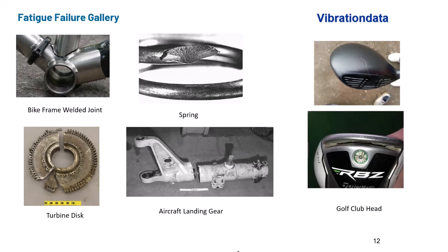The pilot has to do a slight pitch up or flare of the nose prior to landing so that the back wheels touch down first, and then the nose gear following that. All those factors will determine the G level. Now, the G level in landing is monitored on all these commercial flights that you've taken. If the G level is high enough, that will trigger inspection and maintenance. So think about all the different landing shocks, especially the hard landings, that the aircraft landing gear has to endure. That can, in some cases, cause fatigue cracks and failures.